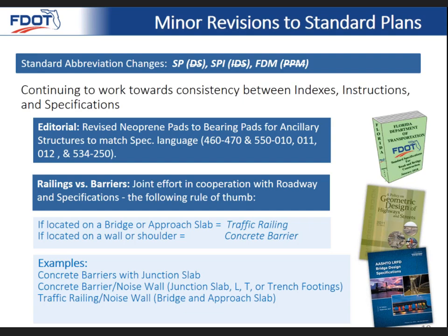Consistent naming conventions with the specifications, the generic naming of traffic railings that Richard mentioned earlier, where the traffic railings that are located on the bridge remain traffic railings consistent with the AASHTO bridge design specification, and then those that are wall or shoulder mounted, which might be considered more roadway-based railings, are named concrete barriers.